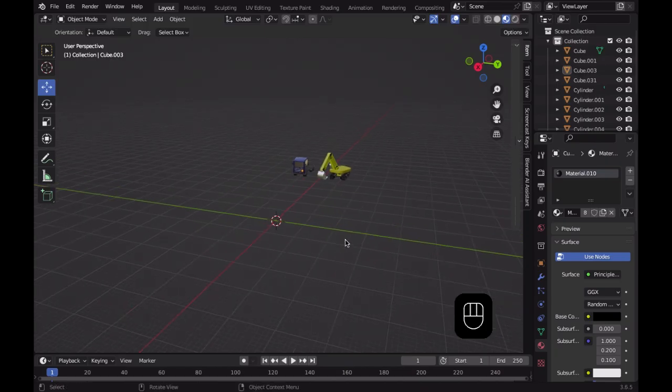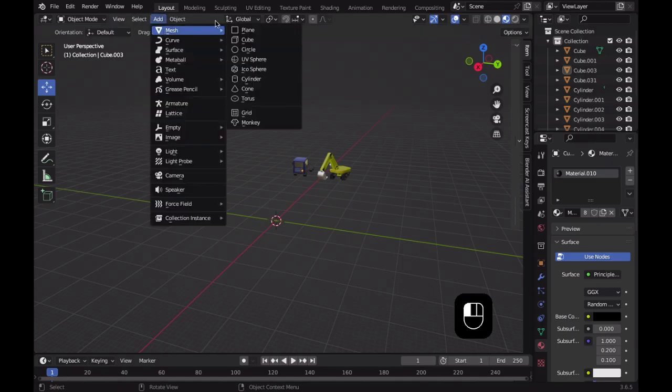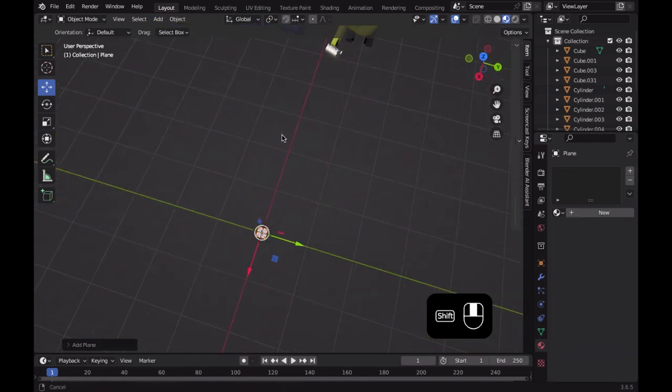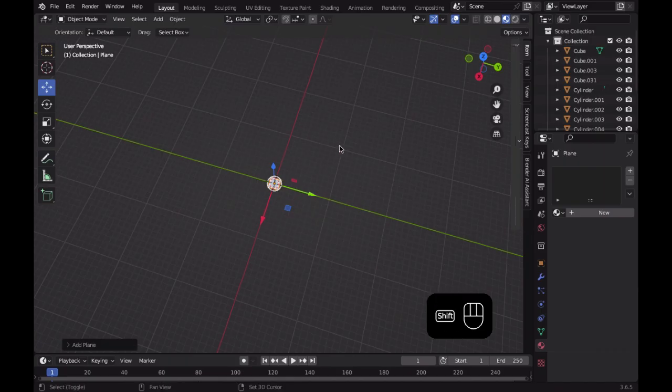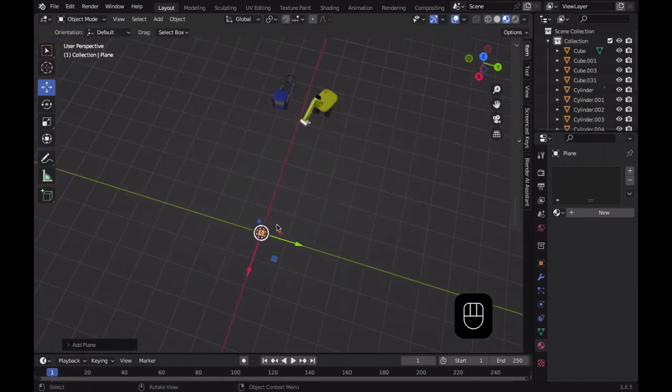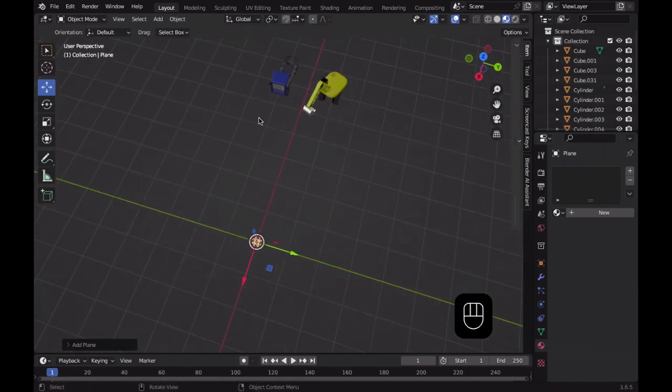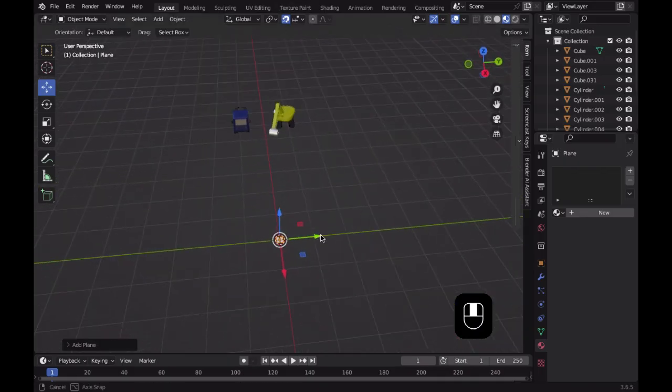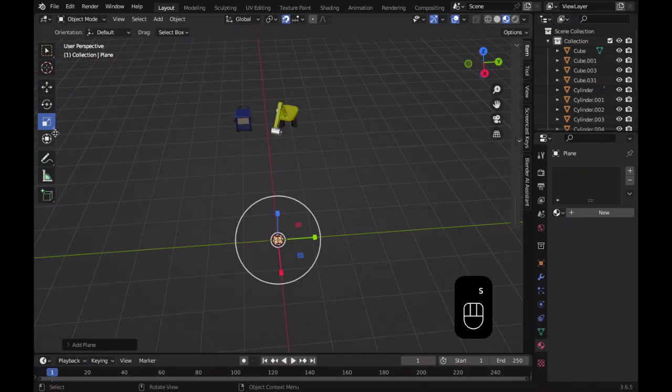Anyway, let's go. So first of all, what we're going to do is we're going to click onto the add menu, and then we are going to add a plane on the mesh menu and plane, and then this should spawn this little thing here. Let's just scale it to about, well, click on this tool up here, so on top of your screen, the middle should be this little snap thing. It should say snap, and click on that and it should make this blue little thing there. Then what we do is we click S, which goes into this menu, unless it straight away makes you able to scale it. Mine does that because I like it.